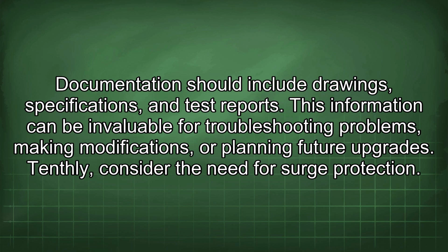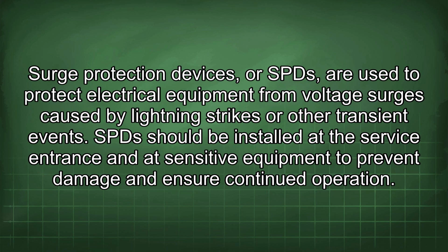Tenthly, consider the need for surge protection. Surge protection devices, or SPDs, are used to protect electrical equipment from voltage surges caused by lightning strikes or other transient events. SPDs should be installed at the service entrance and at sensitive equipment to prevent damage and ensure continued